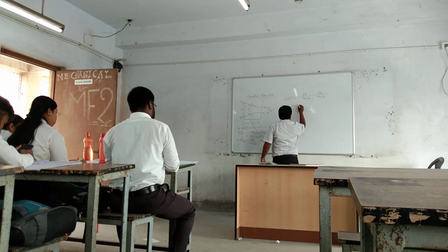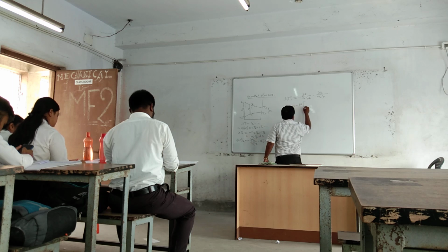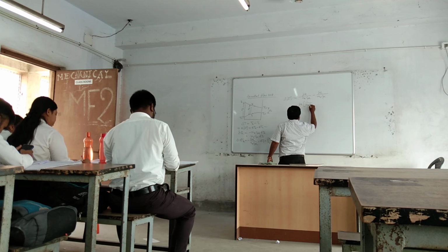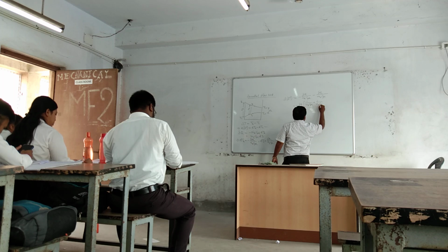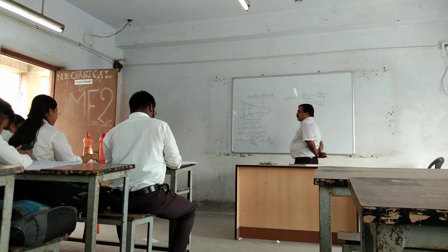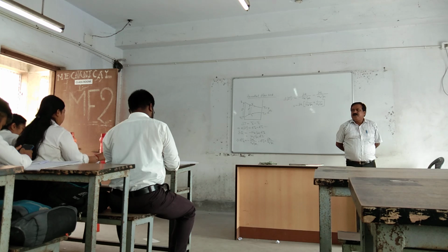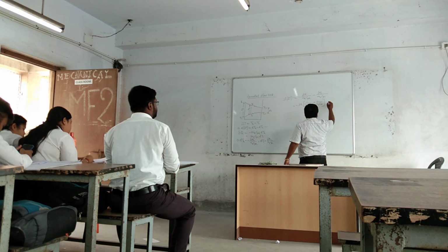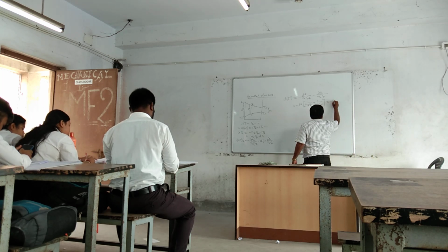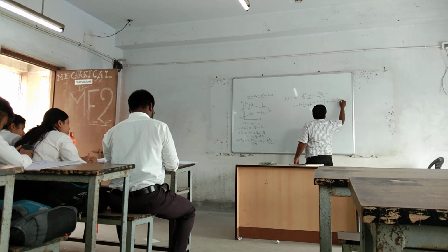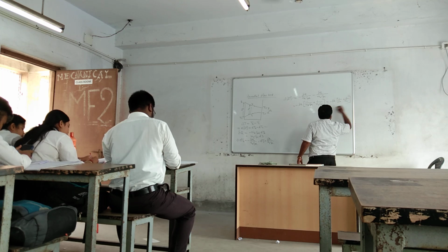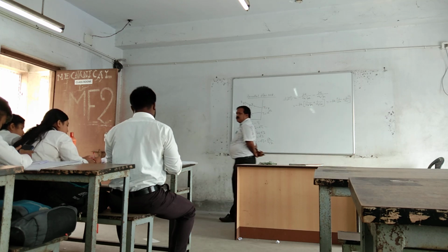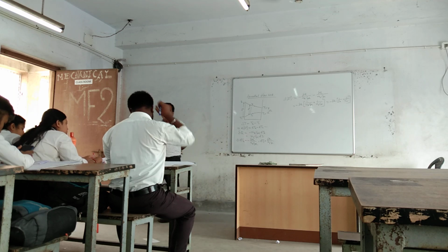So we can write minus delta Q into 1 by m dot H CPH plus 1 by m dot C CPC. Can you write this? Yes. m dot H CPH is nothing but capital CH, so minus delta Q into 1 by capital CH plus 1 by capital CC. Okay?